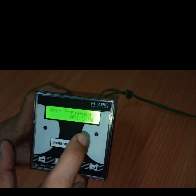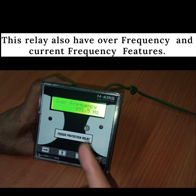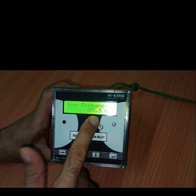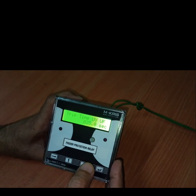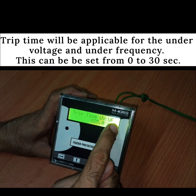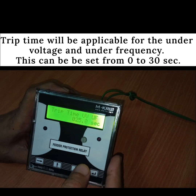Over frequency, this relay also has over frequency and under frequency protection features. So here we can set over frequency limit, which can go up to 52 Hertz, and under frequency can go up to 48 Hertz. This is the trip time which will be applicable for under voltage and under frequency. This can be set from 0 to 30 seconds.